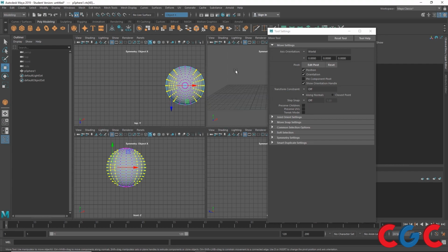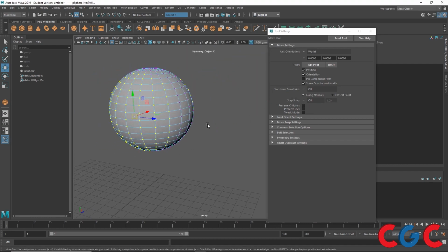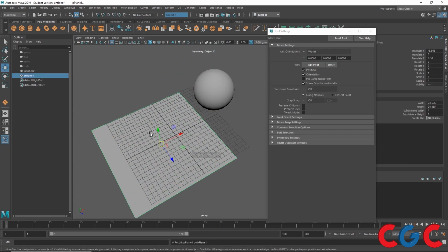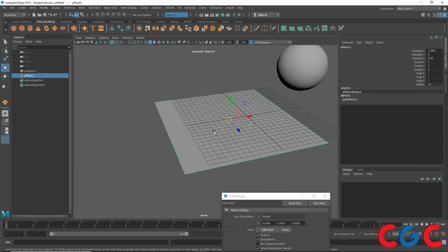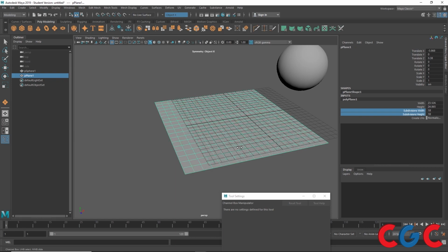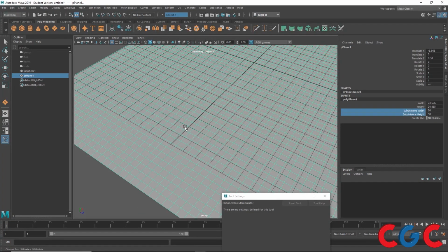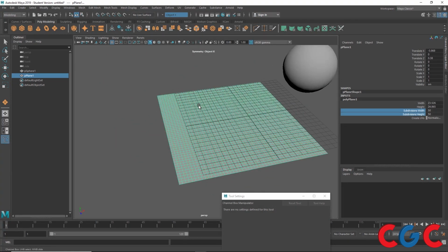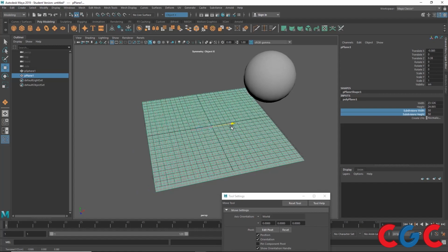So then we have one more option, like if you want to select gradually. For example, I'll create a plane. Right, using this plane, how do I add or increase or decrease the component amount? You can go to polyplane. Here you have something called height and width. So when you increase or decrease the height and width, you can see the edges are getting created. More edges means more vertex and more faces. So for example, here I have a plane with many vertex and many edges.